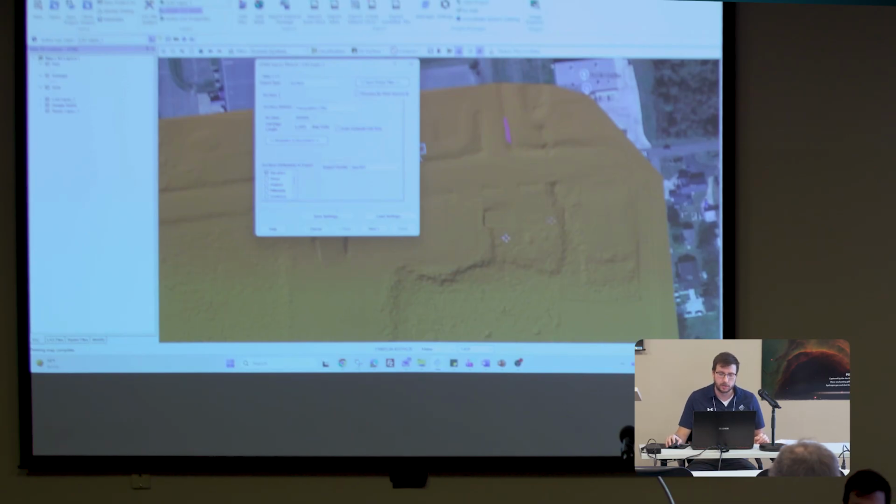So let me just talk about that for a moment. You can choose an ASCII raster here, or, and this would have to be at the point cloud, of course, go to points up here at the top. Choose export format ASCII XYZ, and you've got some additional options there. But you would need to do that after you've done some thinning of the data.